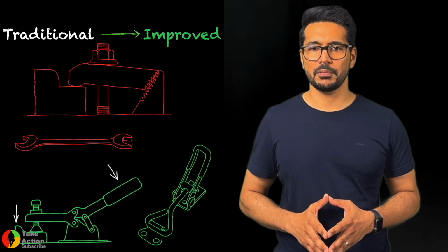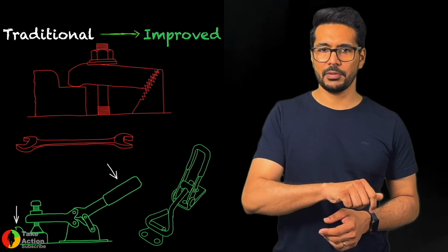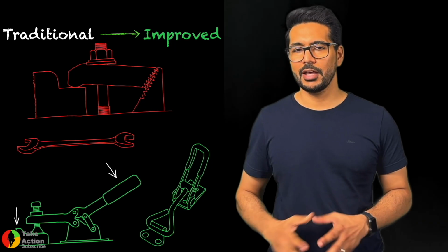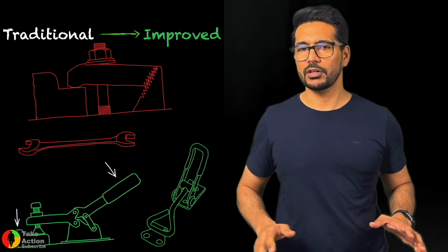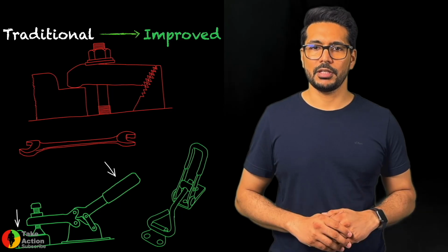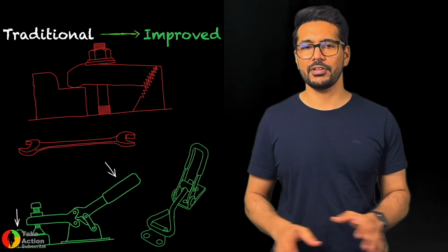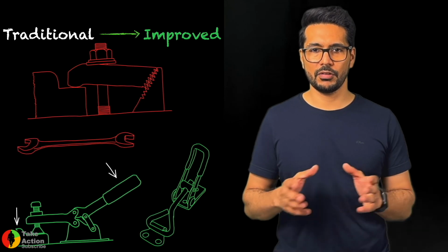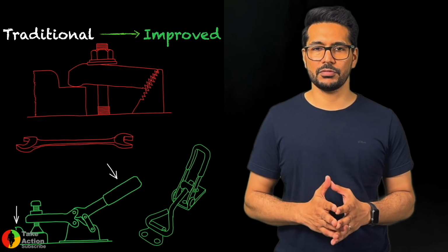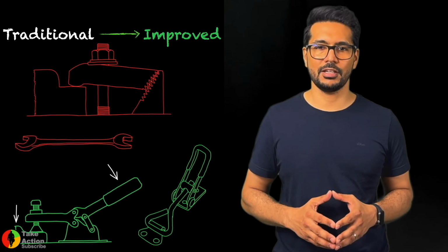They can be simply clamped by hand and very easily opened, and that eliminates the whole work of loosening, removing the packing plates and replacing the packing plates as per the height of the parts. Everything is eliminated if we have these state-of-the-art clamps which are very easily available in the market.